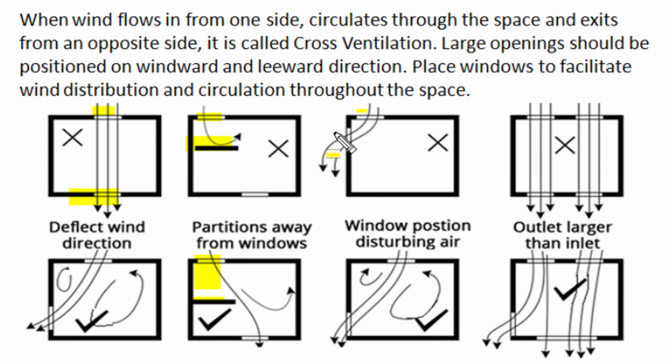If windward and leeward directions window are very close to each other, then majority of room space remain deprived of air circulation, and if we place windward and leeward window quite far away in room envelope, then it will ensure good distribution and cross ventilation. For good swift movement of air, the windward opening should have smaller cross section, and leeward, where wind go out of room, should have a larger cross section.